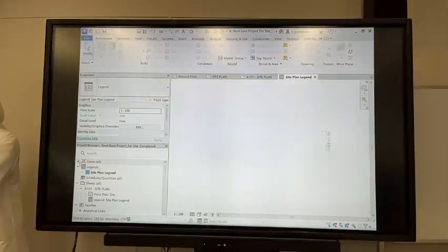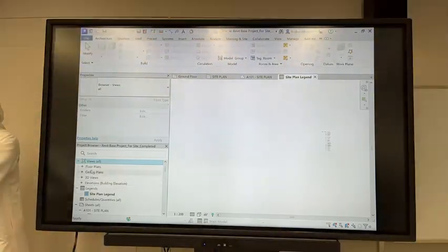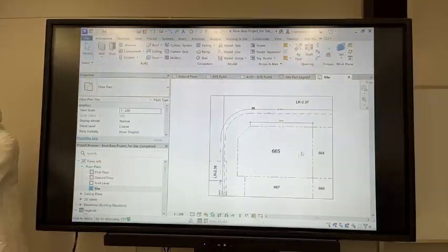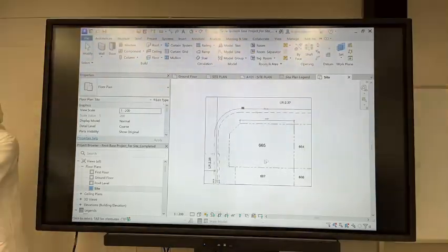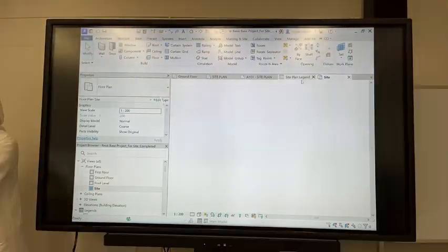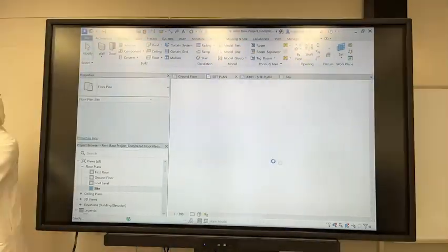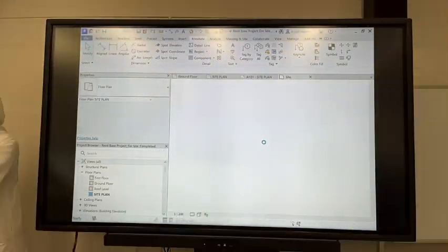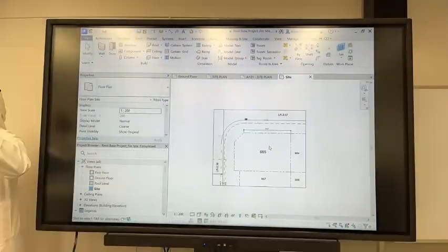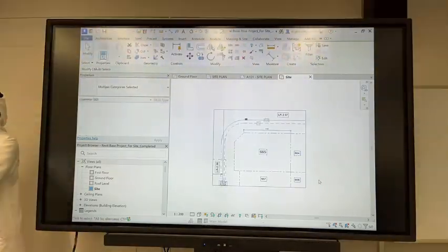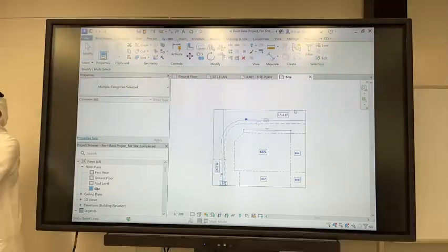Okay, so if you open Views, Site Plan, assuming this is the finished one, it's not. What you do is, now turn off the site in the new and the old. Okay, so I have site plan, this is my new one that has the building. And this is the site plan view that has all the information we selected last week. You select everything, with your legend. Yes, with your legend.